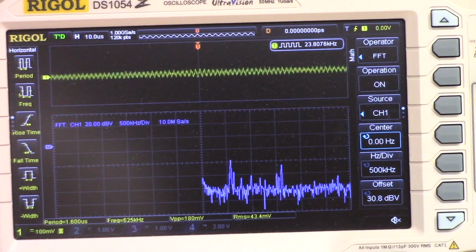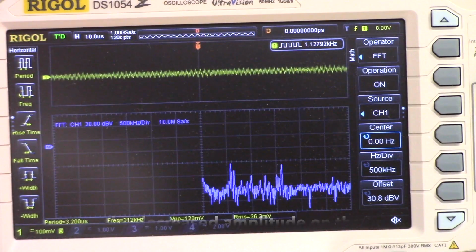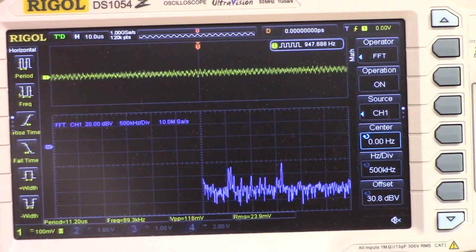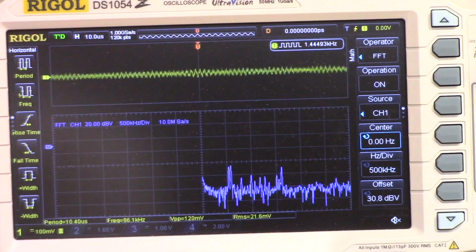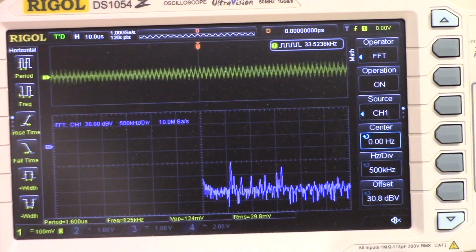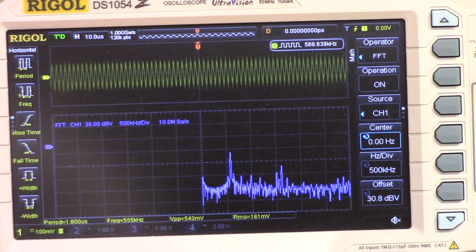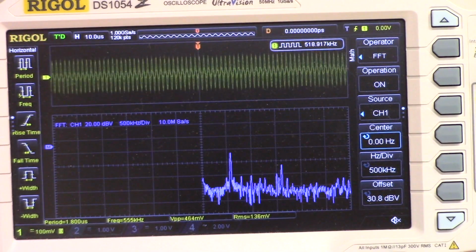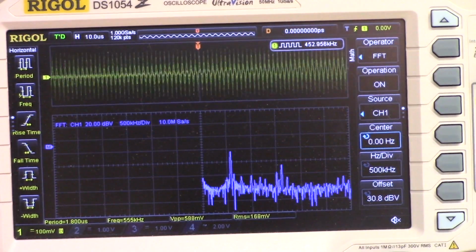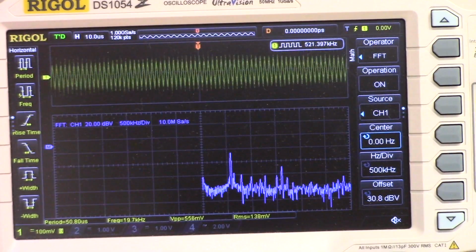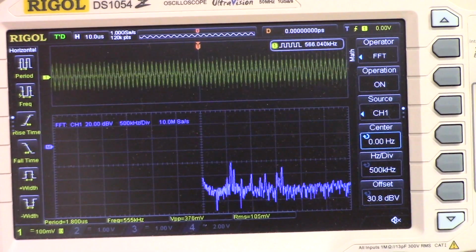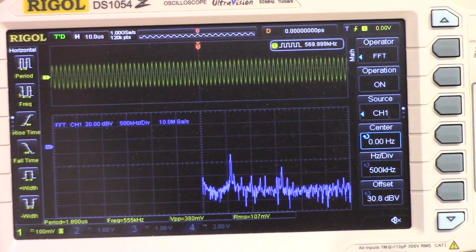So let's detune the circuit now and look at the spectrum. All of the stations seem to have peaks that are more or less equal to one another. Some are taller than the other, but they're not radically dissimilar. But now as I start adding capacitance to the circuit, and I hit my first resonance there, you see this one spike right there peaks, and that's the spike at 580 kilohertz. 570, 580, I forget which the station actually is.